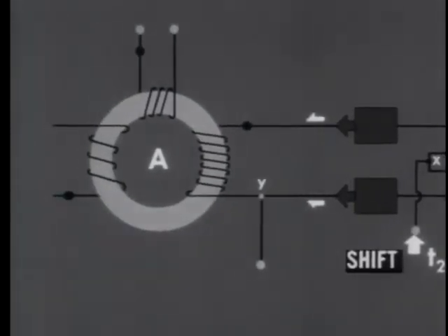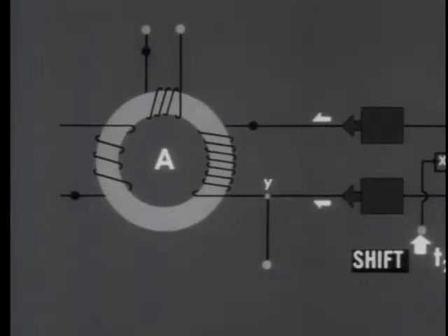But the lower branch does not get there. Instead, it flows out of the circuit at point Y. The upper branch, however, does reach core A, entering its output winding as a dot pulse. Since core A is in the binary 0 state, that is, its magnetic flux is already negative, an additional pulse of dot current will have no practical effect on the core. There is a counter EMF induced in the winding when the pulse is applied, but because the change in flux is so slight, the counter EMF is negligible.